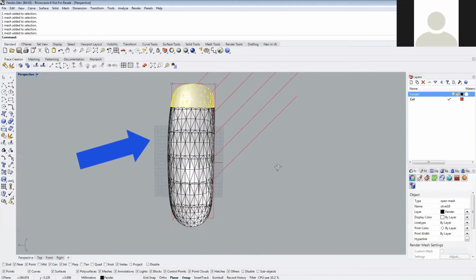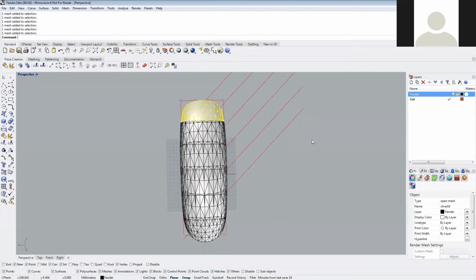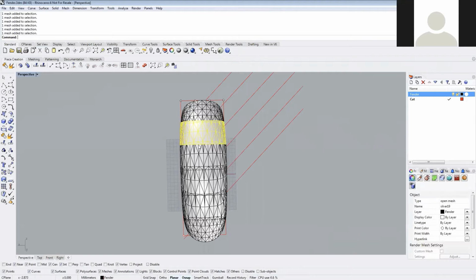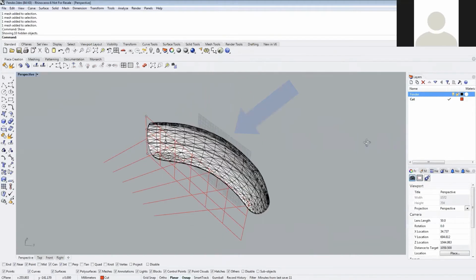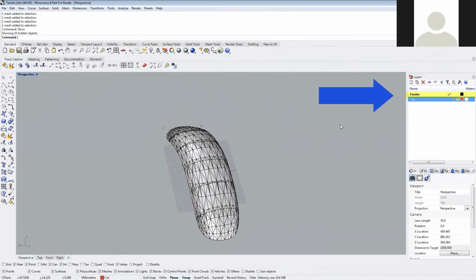So it's a bit more preparation. This isn't completely necessary for the flattening aspect, but when we start considering ply books, and we're going to look more at ply books at our third session next week, we really want to be able to differentiate these different plies from one another. So first of all, we're going to bring back all of our different layers here. And now we're going to turn off our cutting curves for now. We're just going to make the fender the default layer.